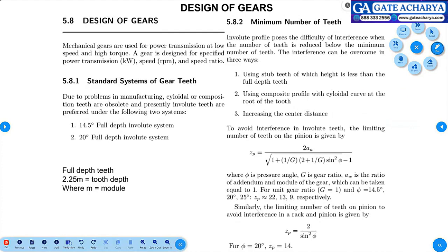Slip coming out. Whereas as far as gears are concerned, there is engagement between two teeth. So we call it a positive drive. There will not be any slip in gear drives. So we call them positive drives.